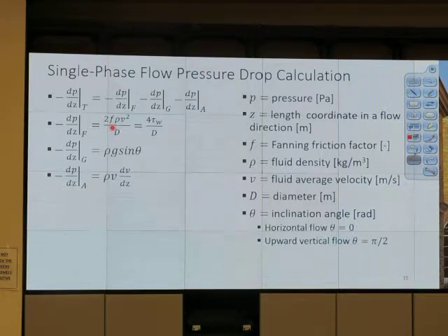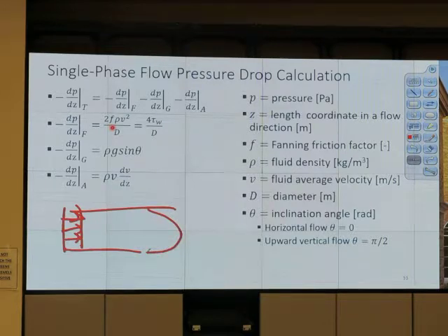Okay. So think about this. When we have a flat profile near the inlet, and we want to change to a parabolic profile, we need some additional energy, right? But later on, we don't have to do anything. In addition to changing the shape of the velocity profile, there has to be some energy dissipated to deform the fluid. So when the fluid shears against the wall, we actually deform the fluid element. Okay, that causes a frictional pressure loss. So if we want to use this equation for developing flow, there has to be a correction factor for friction factor.